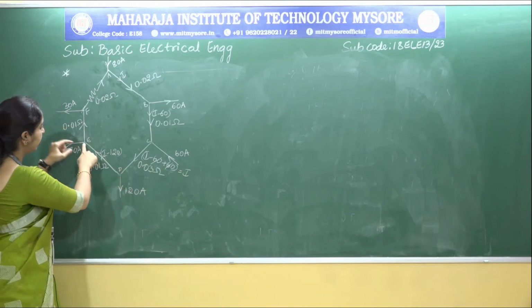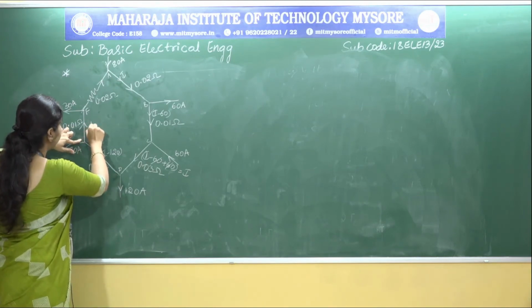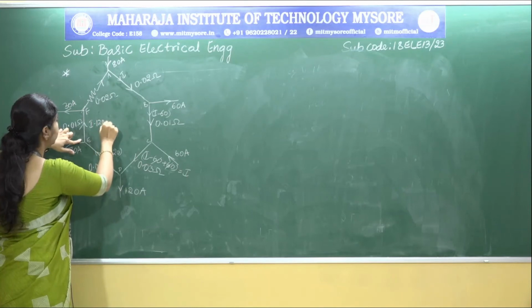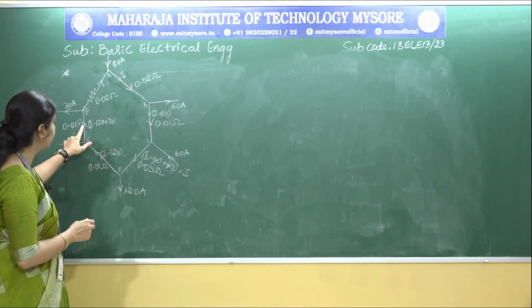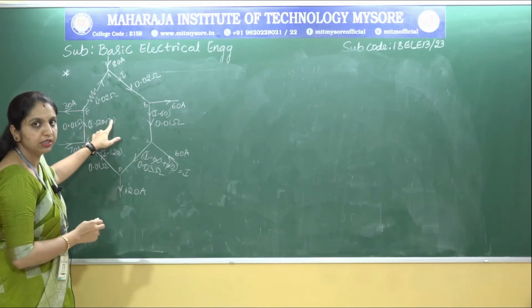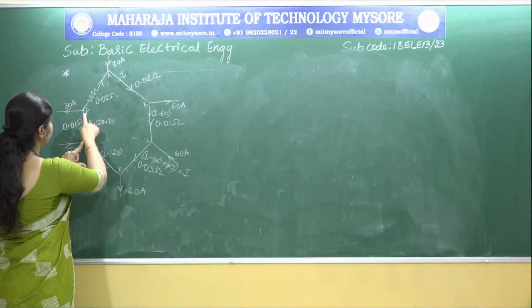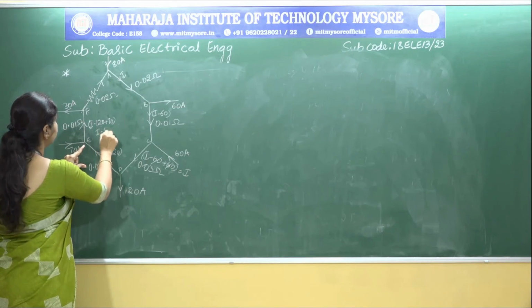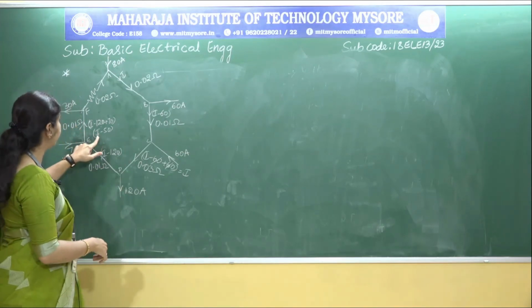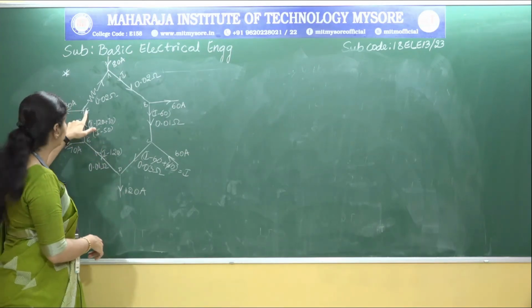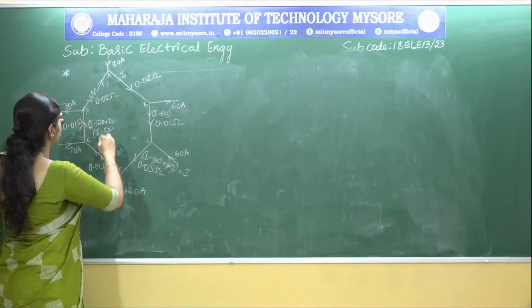Now I minus 120 is entering the junction, and 70 current is also entering the junction. So we call it I minus 120 plus 70. The current passing through 0.01 ohm is I minus 120 plus 70, because 70 current is entering the junction. Here we get this as I minus 50. I minus 50 is entering the junction and 30 amperes is leaving the junction.